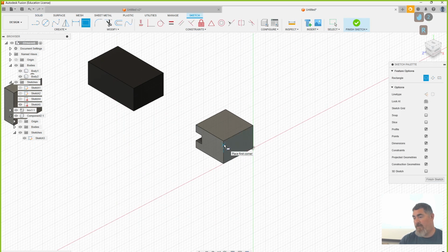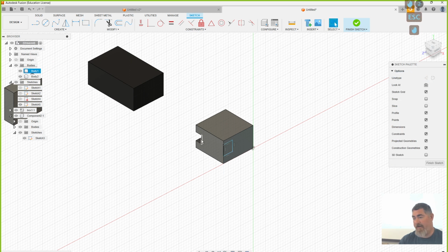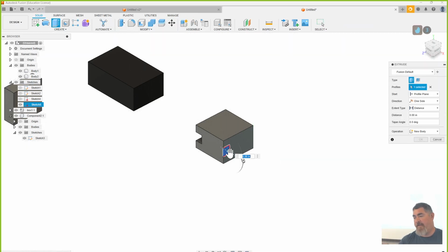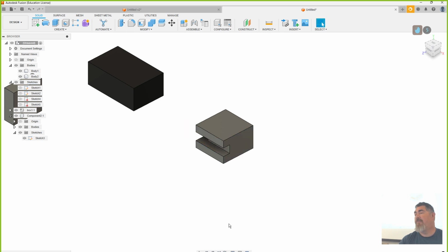Again, draw from a rectangle, and then just project that line, right? Snap to the top of the line, snap to the bottom of the line. That way my height is locked. When I dimension here, just call out my D11. So it's using that same measurement that I've typed in earlier on D11. And then I can cut that way.